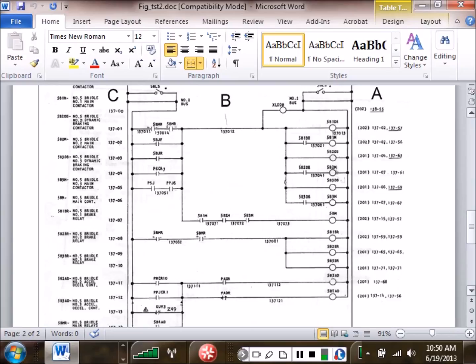Solid strand wires are easier to terminate. To terminate a solid strand wire, we usually just grab our lineman's pliers, put a hook in it, and screw it down, right? You understand?